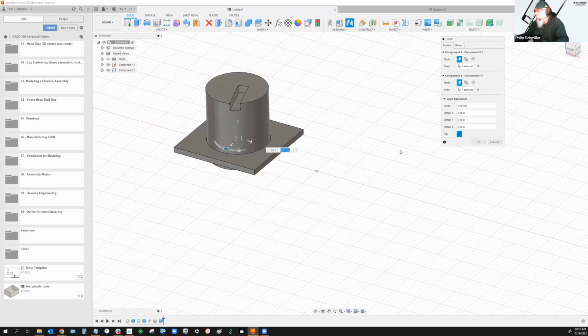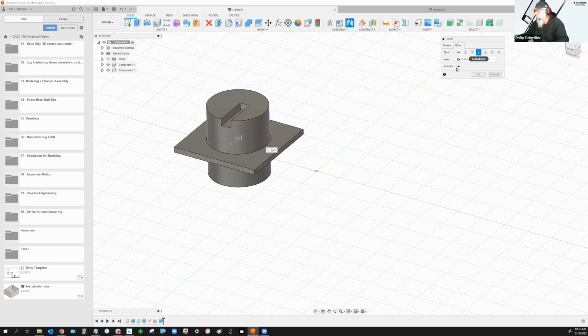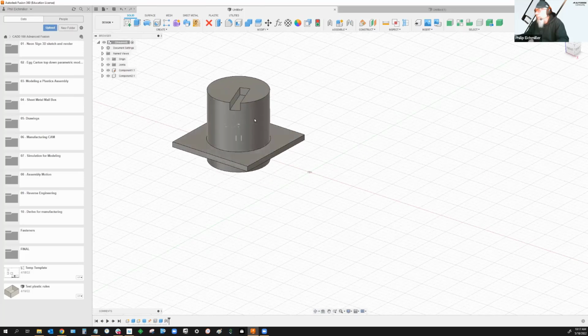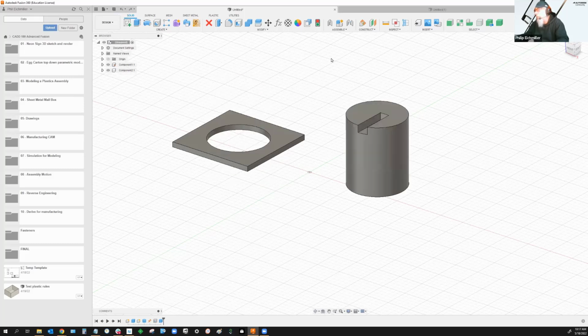And so because this is cylindrical, it has the ability to slide up and down and rotate. So I can also set a relative position. If it needs to start at minus 45, that's just where it lives. You can use the joint alignment to pick that out. So now it moves up and down, and any movement away from that 45 degrees is just the starting position of it.